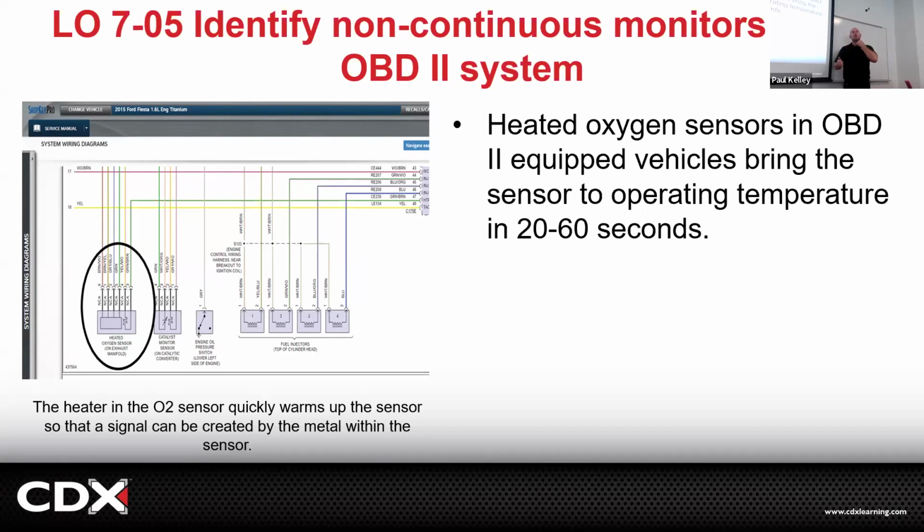Could it be the heater? Yes, and that's the most common. Could it also be a connector? Could it be a chewed wire? Could it be a bad connection? Could it be an open in the ECM? Yes, so we want to do some basic testing, right?